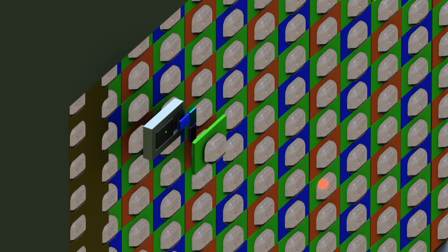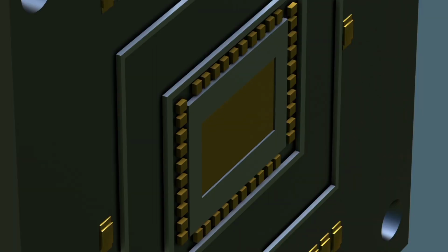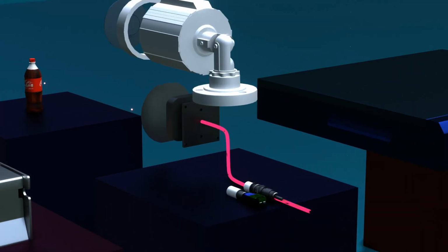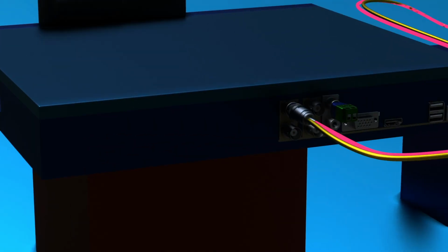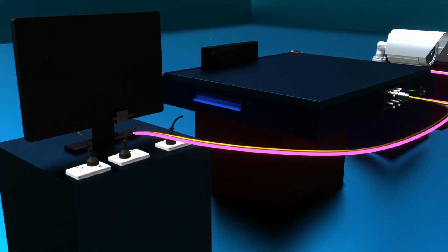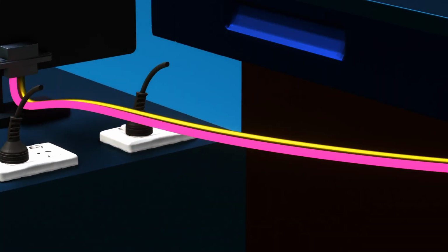In an analog CCTV system, the video signal travels through a coaxial cable along with a ground connection via a BNC connector to the DVR. From the DVR, the video output is sent to the monitor using an HDMI cable connected to the monitor's HDMI port. HDMI is commonly used for high-definition output ranging from 1080p to 4K resolution.